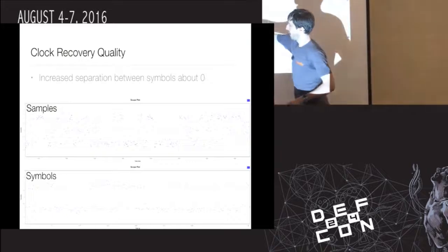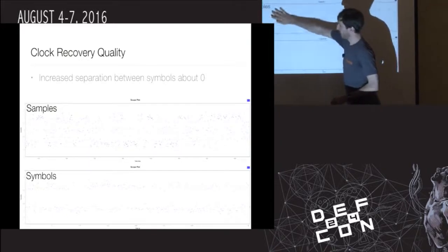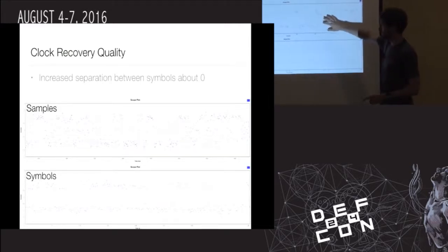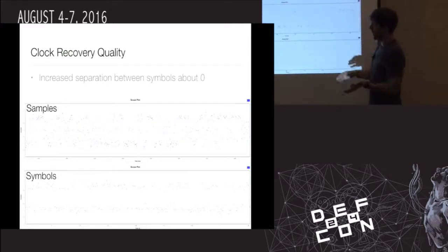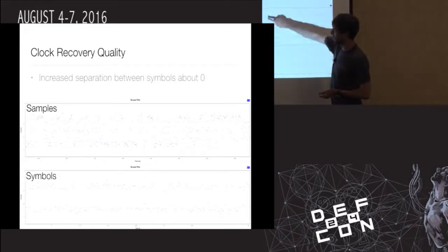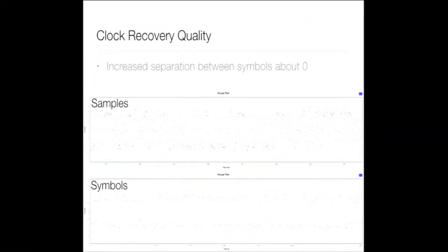We're purely just looking at the samples coming in on our channel. And you can see that they're scattered all throughout between 1 and -1. So that means we've got them in the right range. We're essentially doing FM demodulation on this, and then adjusting the deviation appropriately, or the gain on that, so it falls between these normalized values.